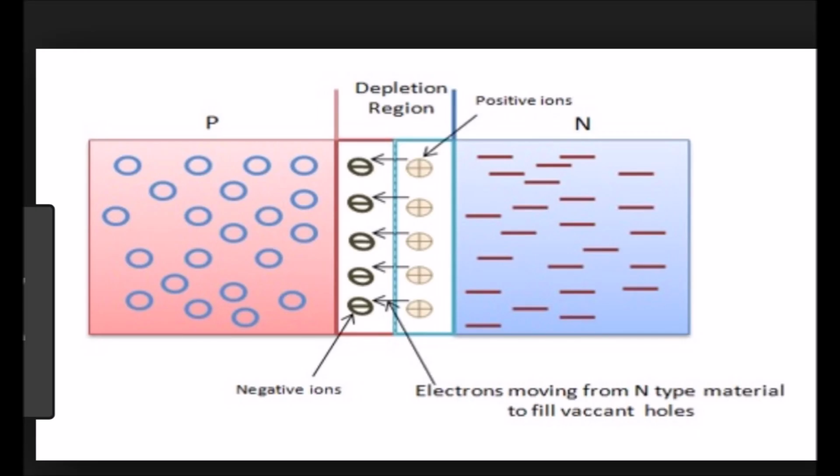Depletion region, that's the next definition. In semiconductor physics, the depletion region, also called depletion layer, depletion zone, junction region, space charge region, or space charge layer, is an insulating region within a conductive, doped semiconductor material where the mobile charge carriers have been diffused away, or have been forced away by an electric field. The only elements left in the depletion region are ionized donor or acceptor impurities.